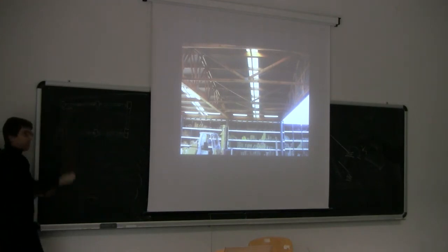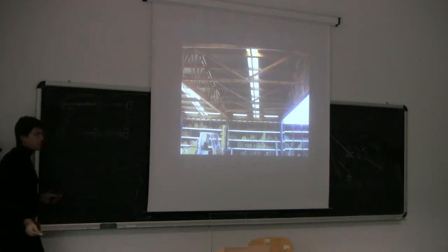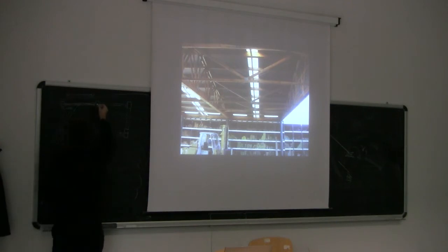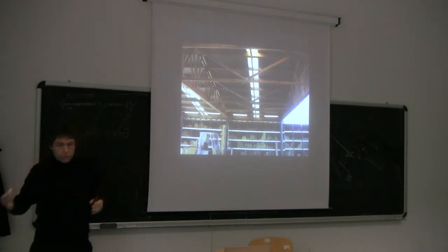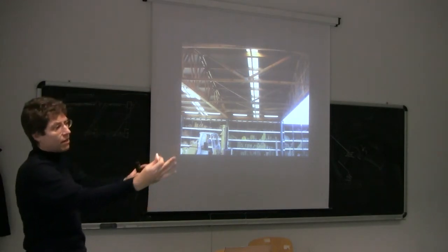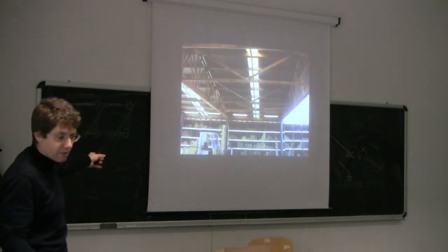So suppose we start buckling. Then this one cannot prevent it. This one can only act as a truss, so it cannot prevent the rotation first. And it will just transfer this kind of deflected shape to the other. So in the end, you would have a global buckling. All the trusses will buckle simultaneously out of plane. That's why one member is not enough.